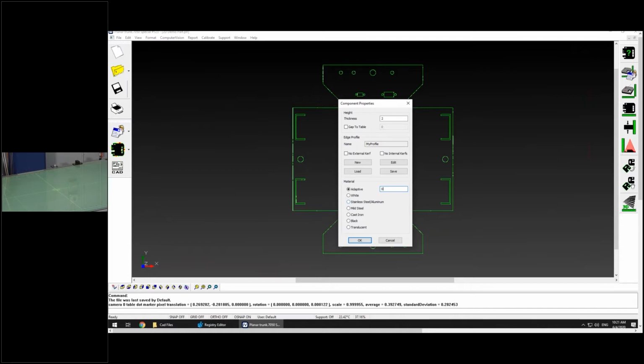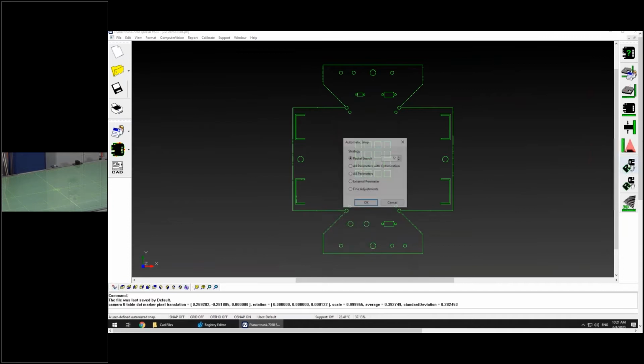And another thing in the 2019-2020 software is going to be the radial snap settings. I know most of you guys that are in this chat, and I believe most of you don't do any radial parts, but the only thing that has changed in the last year is this radial search option. It'll actually let you rotate a part 72 iterations around to try and fit the best method to the part.